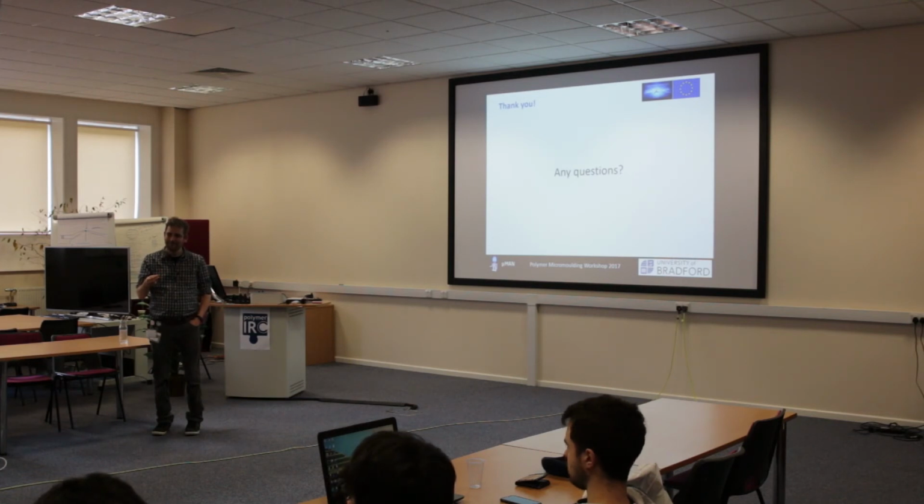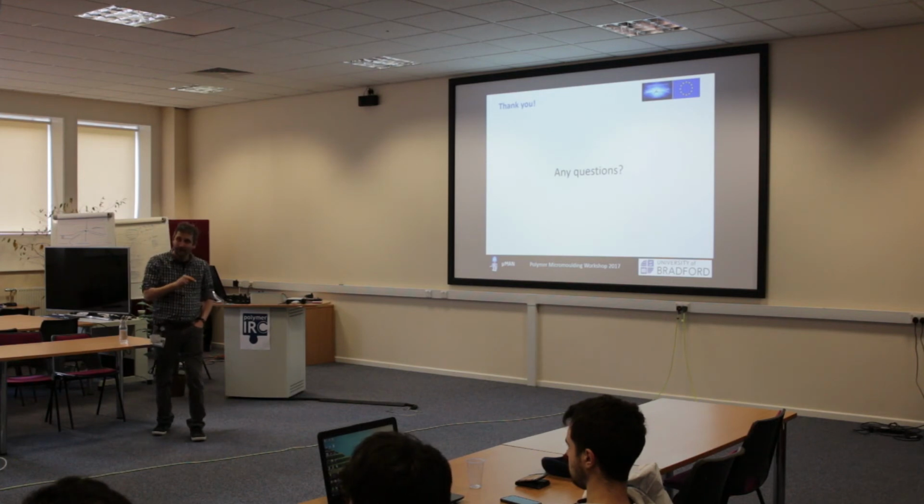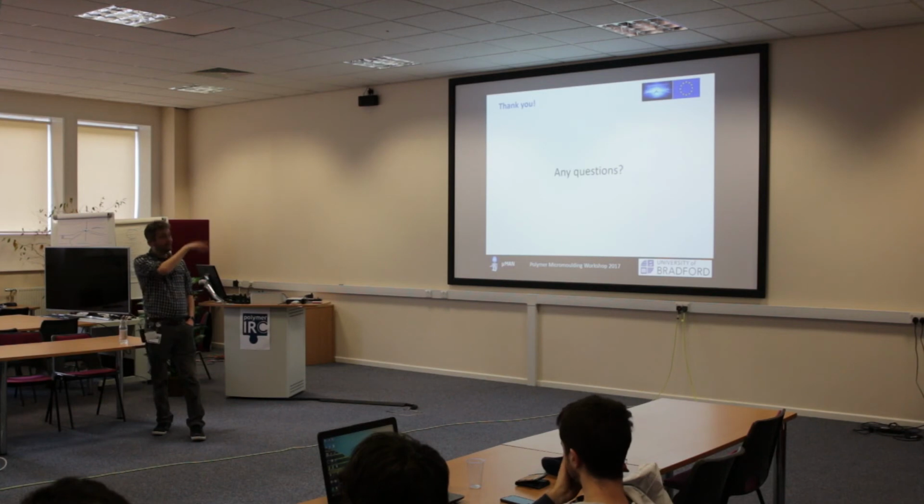See what I mean? There are other techniques, optical techniques, so you'll see the TEM upstairs, transmission electron microscopy, which operates using some slightly different rules, the de Broglie rules, which allow you to get lower than the optical limit. So it's a direct observation, but it actually runs very similarly to X-rays. But instead of being in this reciprocal space, this scattering space, you're actually looking directly. And you can pick up stuff around the angstrom level for that as well.